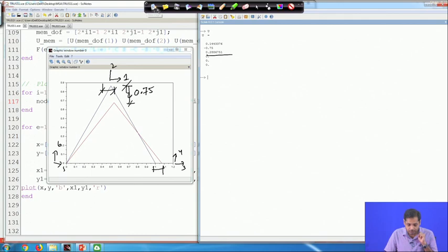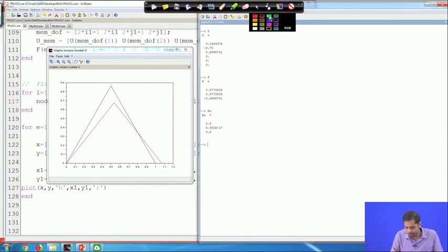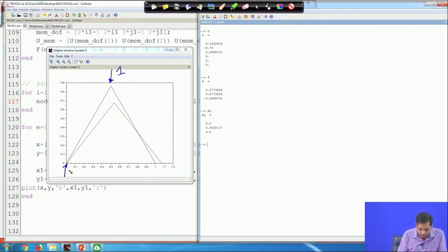Now, once we have the deformed shape, we can also see the load vector. Let us find out the support reactions. The support reactions are these, and we have a load of P here, 1 here. So, naturally the reaction will be half here and half here, and the horizontal reaction will be 0. This is a very small value, which is 0. So, this is consistent.